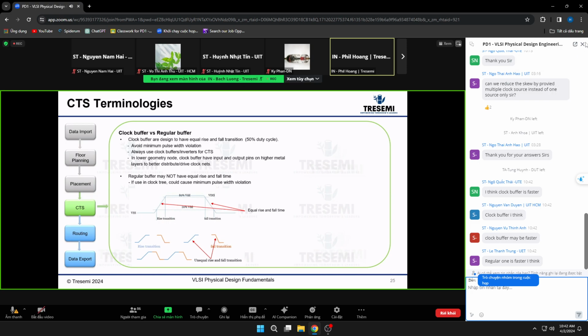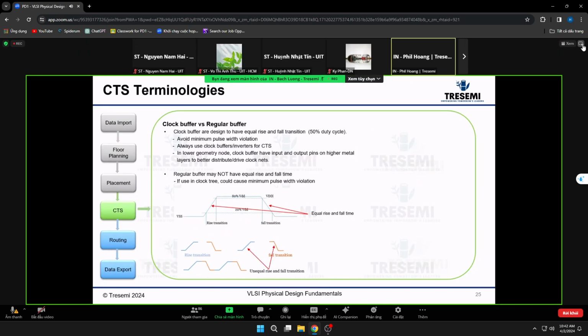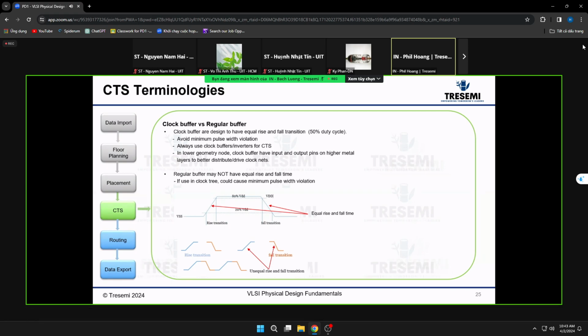So you see this already written down here, right? Like Bud was mentioning, if you have an N and a P for, say, a buffer, meaning the two inverters, you have a P, and usually the P is quicker than the N. So if you want to pull down fast, say you have one X here. So in order to pull up fast at the same rate, then you have to have typically about 2x here, the double width, because the P is weaker than the N, right?